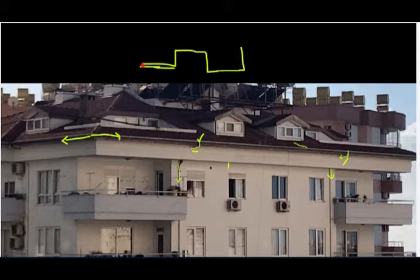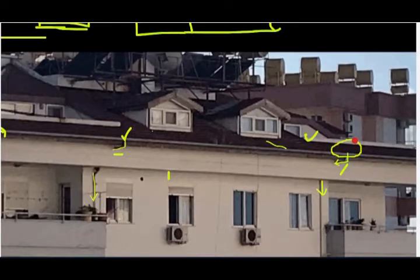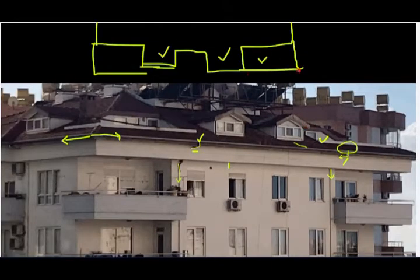Maybe here you will have a bedroom, here you will have a bedroom, and then here you have a balcony, which is this one. This is the balcony that they are using, which is here. And since this is a mirror, the same one we will have on this side. So this is another issue that you have to take care of. And if you look at those balconies, we mentioned that at least 30 centimeters of the slope should be visible from the roof.